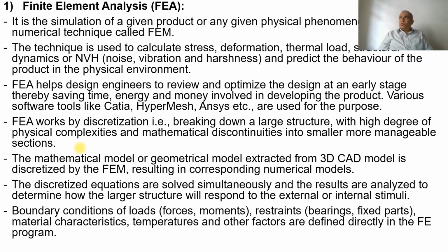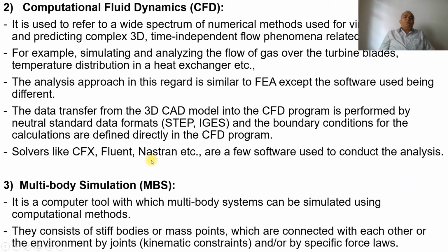Boundary conditions of loads, such as forces and moments, restraints, that is for bearings and fixed parts, material characteristics, temperatures and other factors are defined directly in the finite element program. In case of loads, it will be forces and moments. If it is restraints, it will be bearings and fixed parts.